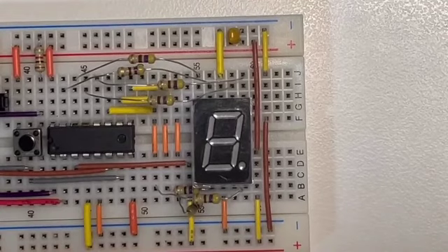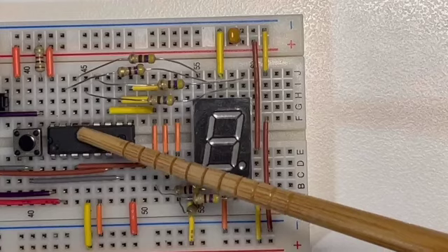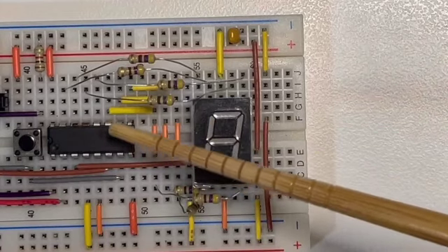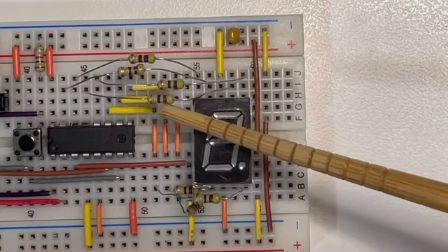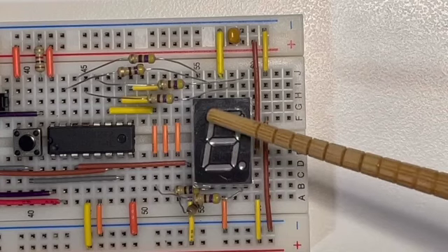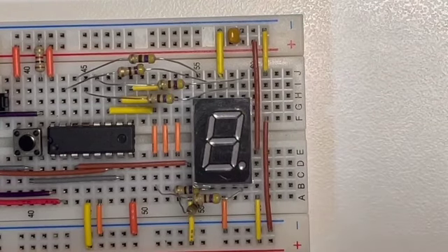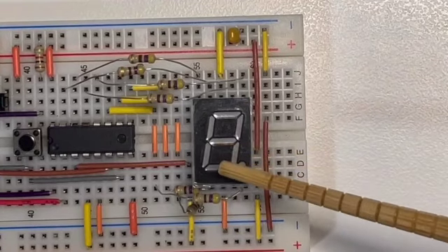The reason why we'd require individual resistors for all the input and output pins of the 7-segment display on the 4511 is because by adding these resistors, we can make the brightness of each individual LED on the 7-segment display have the same brightness. It is also to prevent overcurrent, which could cause the LED bulbs to blow up, causing the need to replace the display.